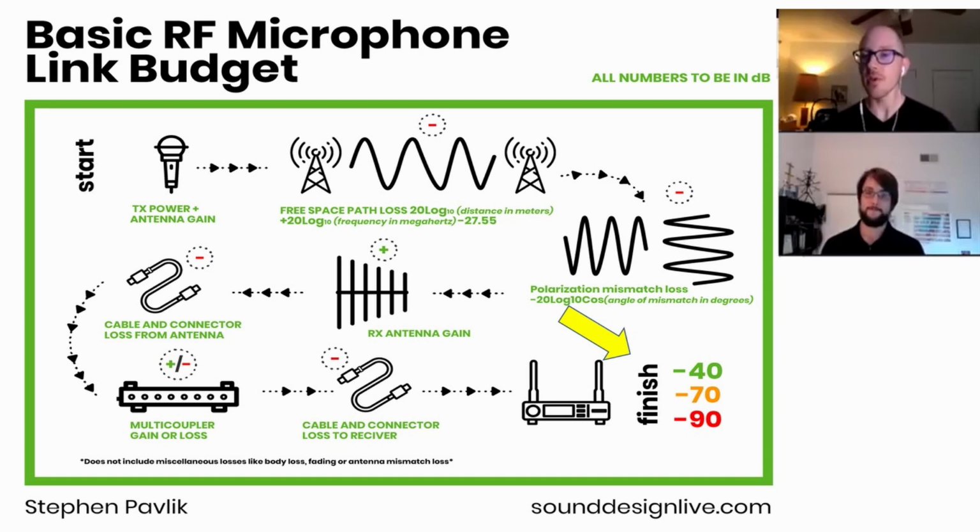Got it. Okay, so at first I was thinking this didn't make sense because all I really care about is my relationship to the noise floor. But now you explaining that a lot of times the noise floor is around negative 100 for many devices, now it makes sense that, okay, I want to be above that, at least like 50 dB, right? Yeah, 50 is great. Like I said, 40 is great. Okay. But you start getting a little too high off that.